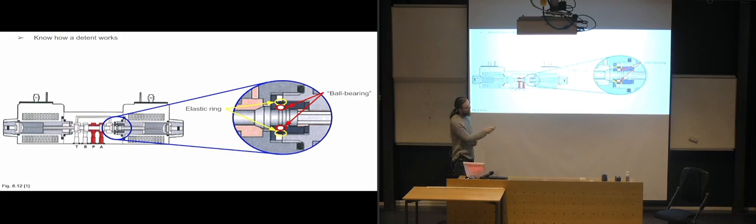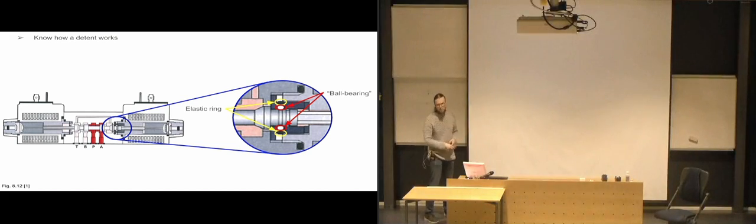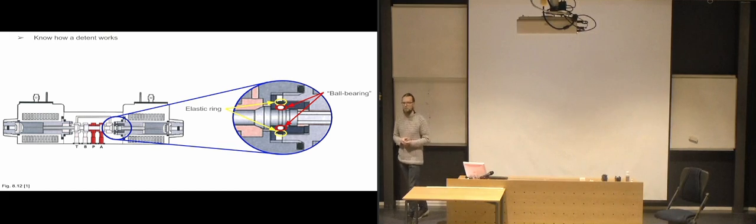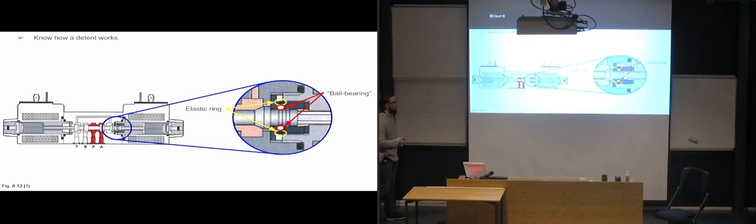So that if we start pulling on the rod, the part in the middle here will force the balls to be expanded outwards, and thus also expanding the elastic ring, until we hit this groove over here, so that they're going to just snap back into that groove and keep that position. So it means that we have a certain amount of force that we need to overcome before we can manage to move the slide.